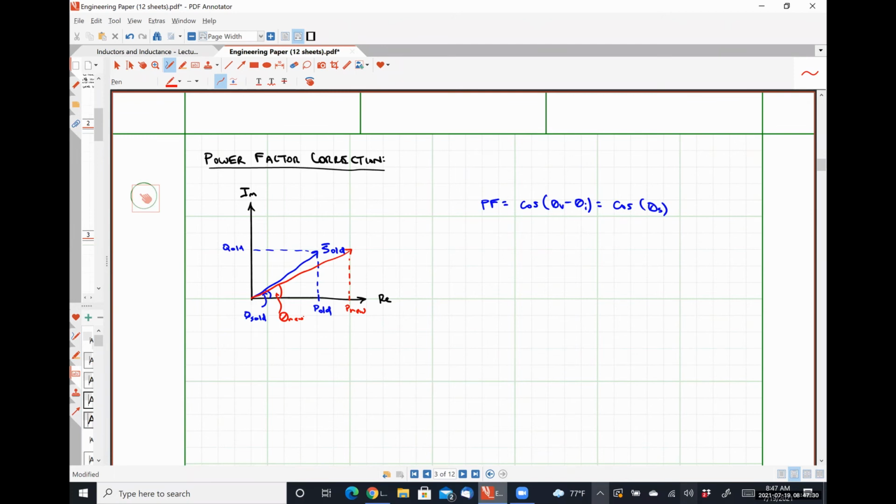The problem with this is not mathematical. Mathematically, it works beautifully. The problem is that in practice, if we raise the power factor in this way by increasing the average power consumed by our load, we are paying a higher utility bill to avoid paying a fine, which makes absolutely no sense whatsoever, right? So mathematically, it absolutely works. In practice, it's absurdly stupid.